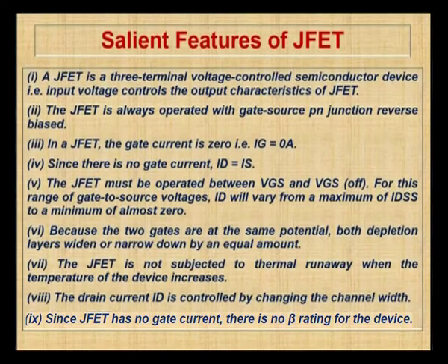The JFET is not subjected to any thermal runaway when the temperature of the device increases. The drain current ID is controlled by changing the channel width. Yes, we are going to change the channel width to change the drain current. A JFET has no gate current and hence we can say there is no beta rating for the JFET. These are the important points that we need to remember about JFET.